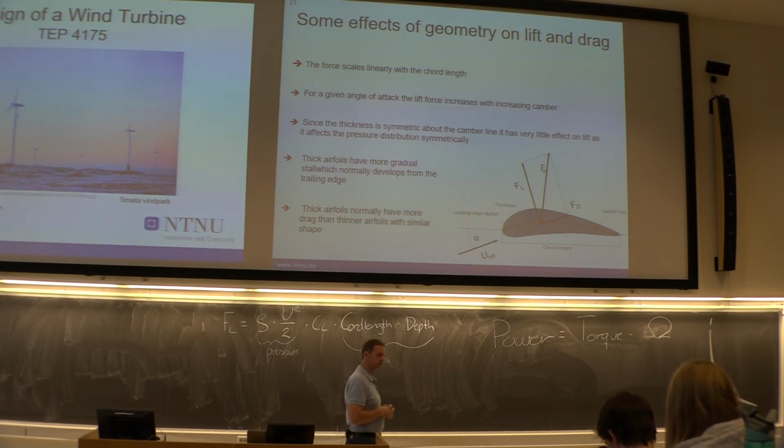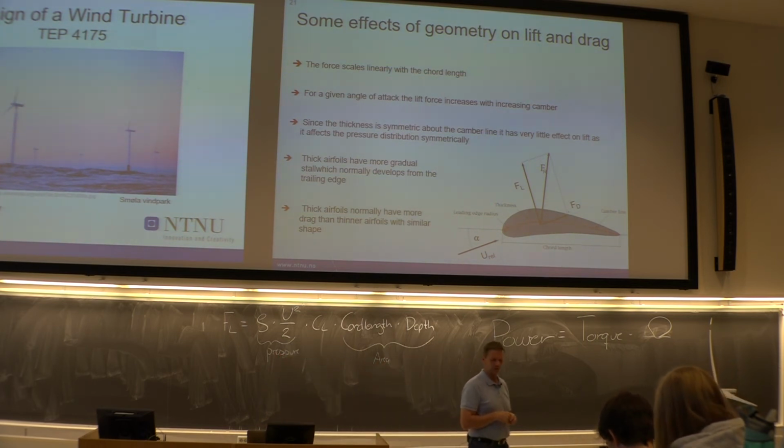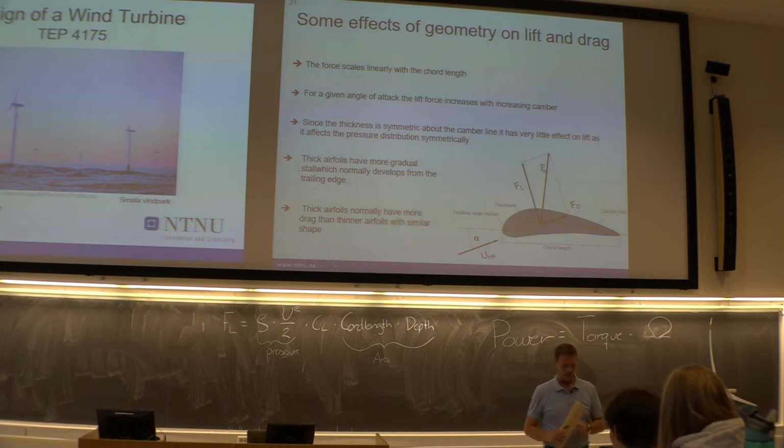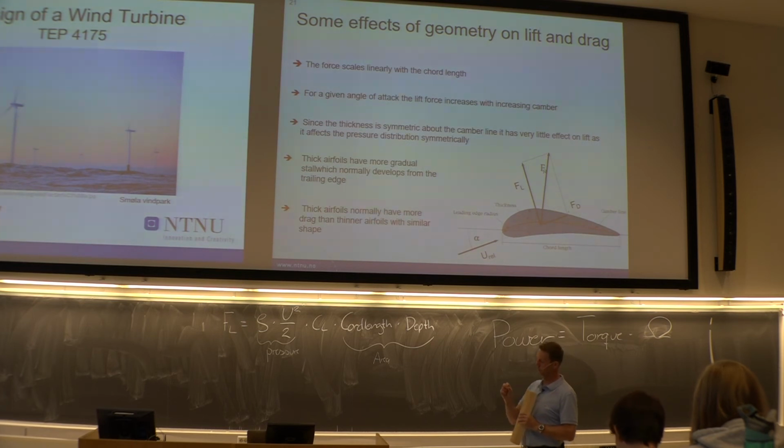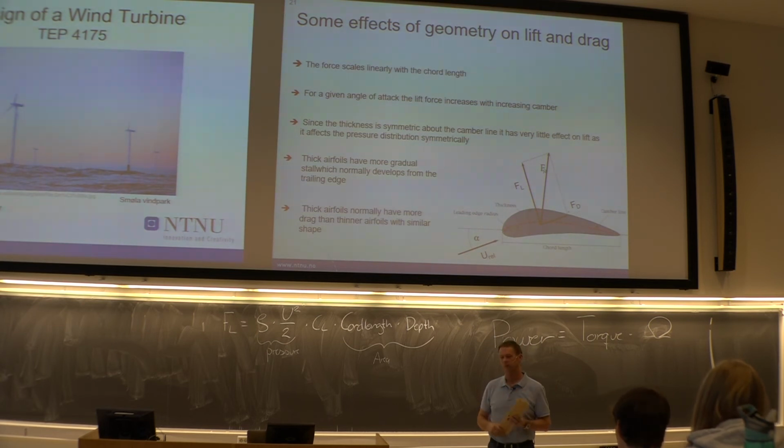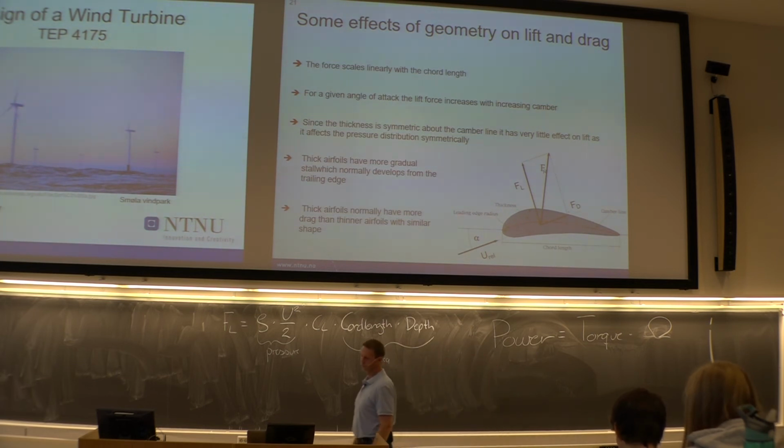Thick airfoils, of course, have a lot more drag than the other ones. We will have to define a minimum thickness for your airfoils, because we have a limit on the CNC machines. If you go below, I think it's 1 millimeter at the trailing edge here, you will have trouble with the machine, which is going to machine it out for you.